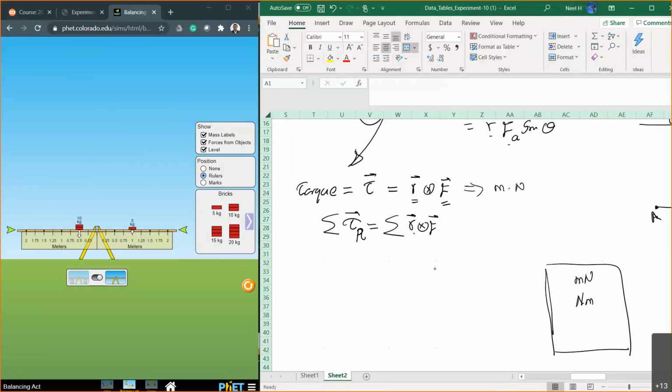The unit Newton meter is actually the joule, the unit of work done. But do not write that unit here, because to consider joules, I have to have a moving object. The object has to move from one point to another, and work done must happen. In this case, there's no work done. Torque can be there, but if the object is not rotating, there's no work done. So the object must move to have work done. Because of that, do not write Newton meter for the torque.